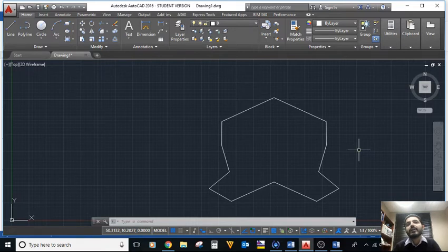You are interested now to know how many layers of asphalt or how many layers of soil or rocks are in this street. So many times, that's what we call a cross section. If you cut through the highway 90 degrees perpendicular to your travel direction, you will be interested to see how many layers you have, and to distinguish each layer, instead of just using colors, you can hatch it.